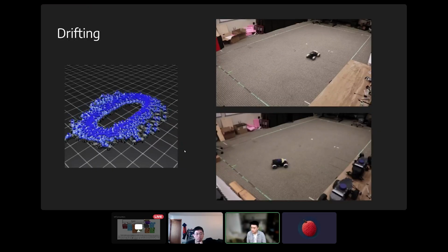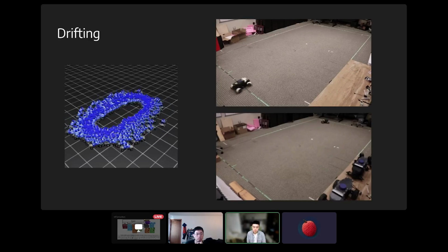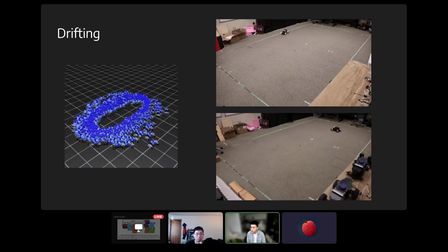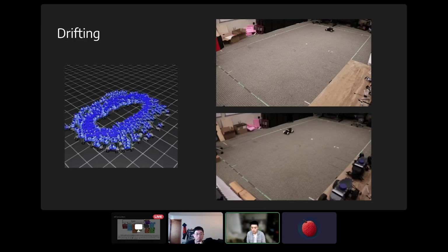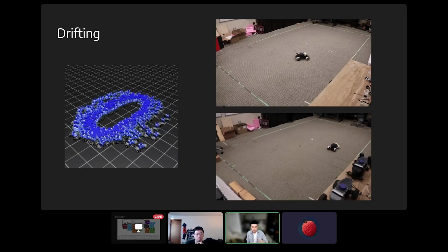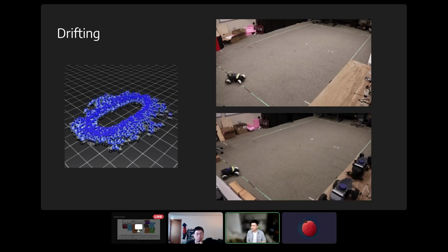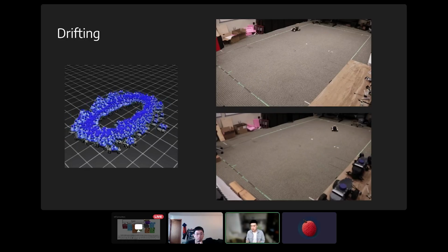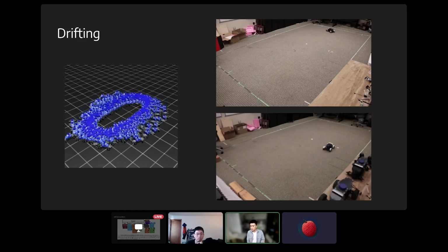Especially for a task like drifting, which is quite dynamic and quite unstable, the performance of the task is really sensitive to the actual configuration of the robot and the dynamics of the robot and how it's being simulated. For instance, we changed the default URDF that we had imported for the musher, which is the blue car on the left, had the steering linkages going right through the wheels, which is completely unrealistic and caused certain steering angles between the real world and simulation to be completely different. So those had to be resolved.